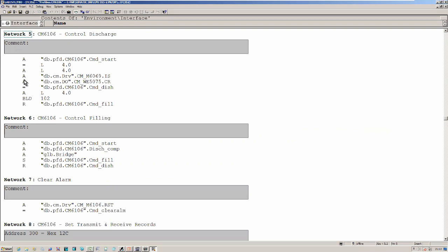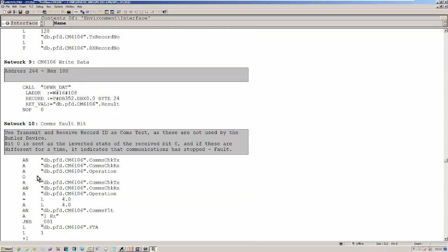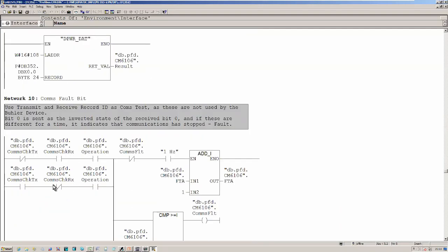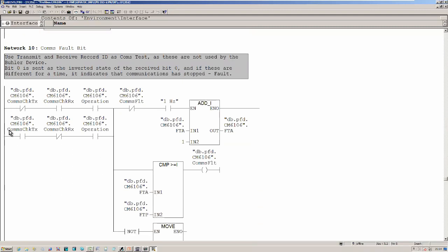So there's AND. And let me just see if I can find some ANDs and ORs. Here's an AND and an OR. If I change from function block to ladder, you can see this is quite a complicated piece of logic, but in ladder, it's very easy to read. It looks like a wiring diagram. You can see that's a normally closed contact. So if that is off, and that is on, and that is on, then the logic will pass. But this is now this and this and this, or this and not that and that.